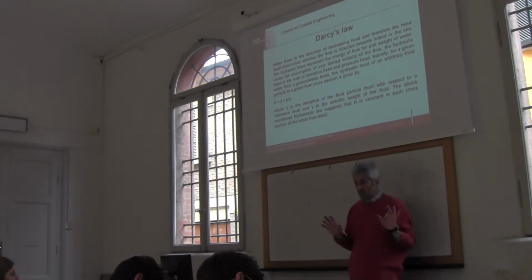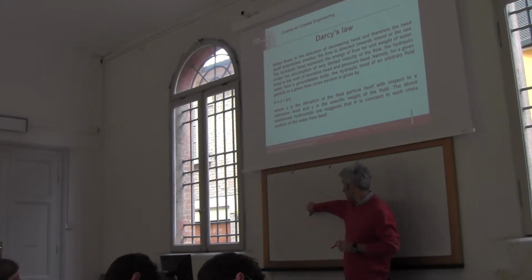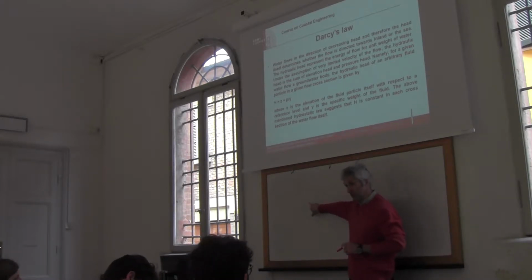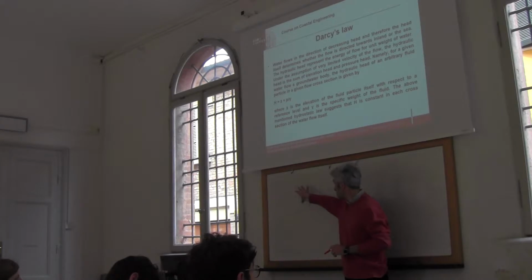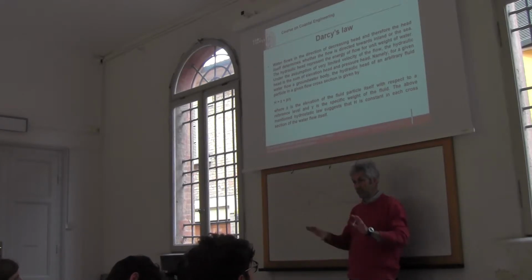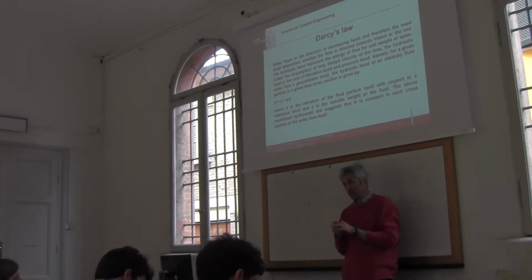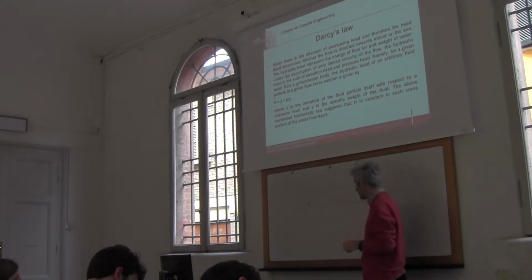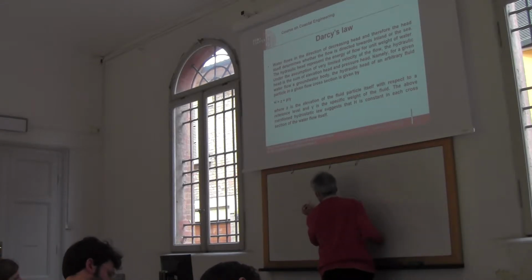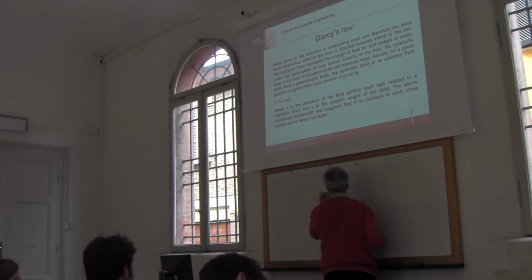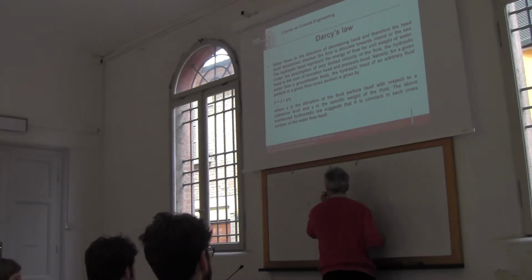The hydrostatic law basically allows me to compute the pressure that is exerted on this fluid particle by both fresh water and salt water. And they are the same, because otherwise I wouldn't be on the interface. This particle of fluid would move if they were not the same. So let me indicate with the symbol H, or I don't remember if in my sketch I used the same symbol, but I guess yes.